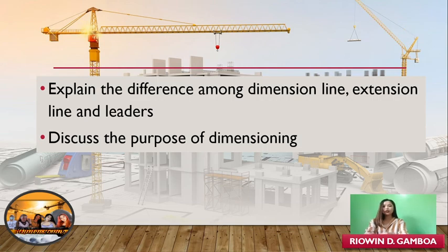Extension lines are also thin lines, showing the limits of dimensions. Dimension line arrowheads touch extension lines, and leaders are more thin lines used to point to an area of a drawing requiring a note for explanation.